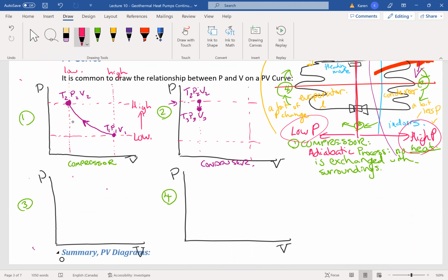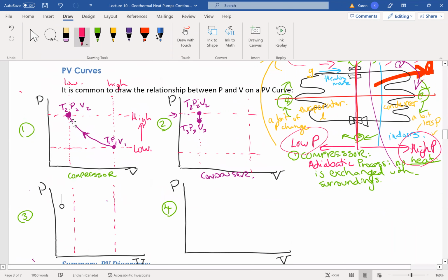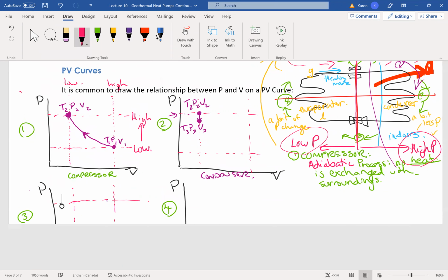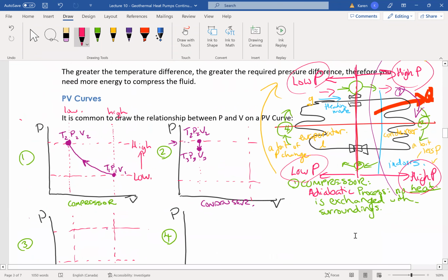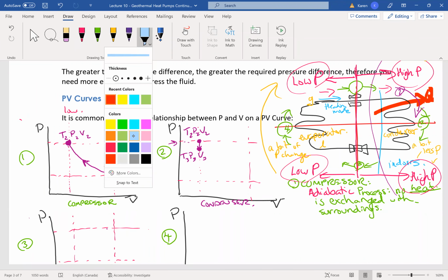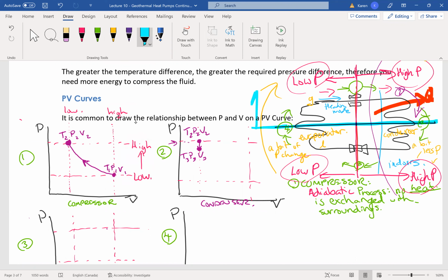So if I say that in general I have some low volume and high volume sides, and some high pressure sides and some low pressure sides, then I should put those on the diagram here as well. Basically I need another line. I'm going to need to really mess up this diagram. I'm going to say that this up here tends to be gas. Well, we hope, because we don't like putting liquids through a compressor. Down here, it tends to be liquid.